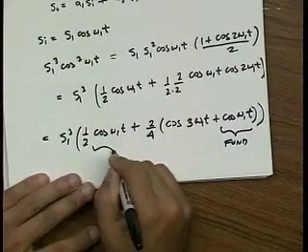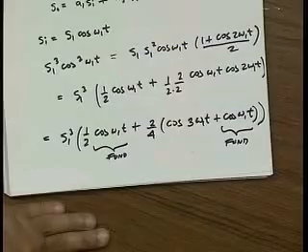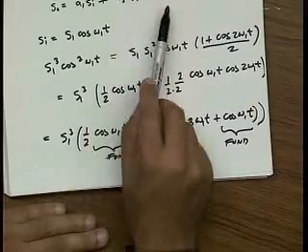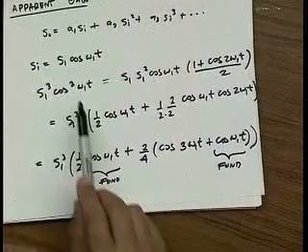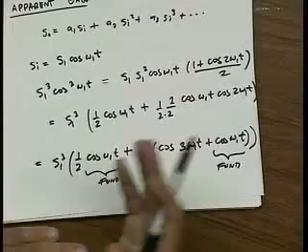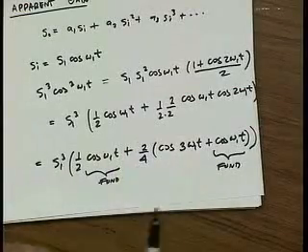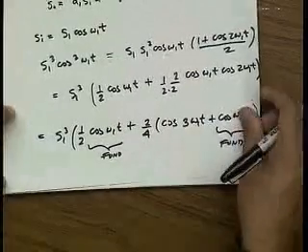And so we see that the cubic operation generates two fundamental signals, and depending on the sign of A3 in this expansion, these fundamental tones could either add to the linear gain term or they could subtract. And so for a compressive nonlinearity, they do subtract. So let's collect these terms.